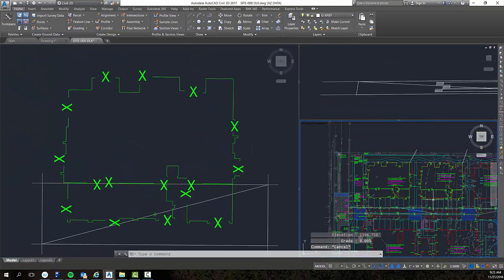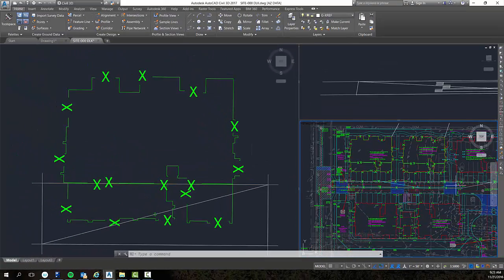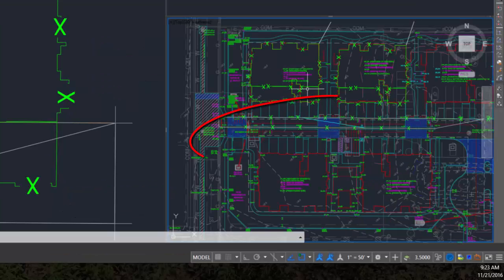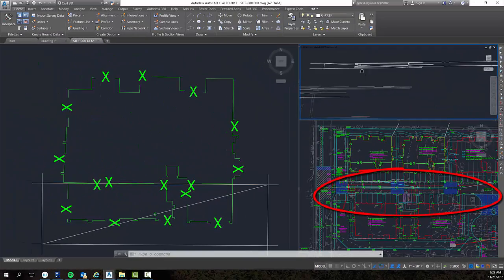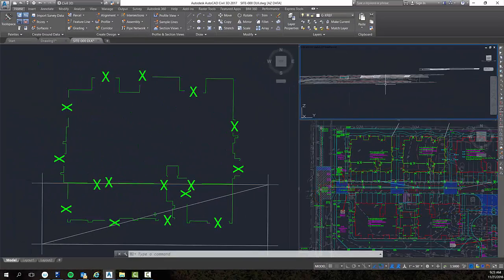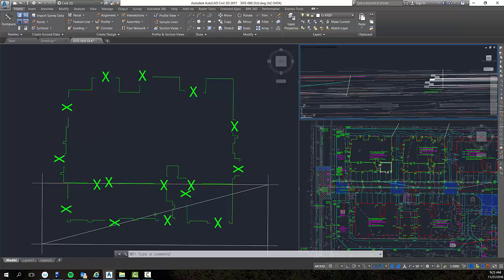So now at this point, we've got this surface here we've already started, so we can start adding this stuff to the surface, right? So let's go ahead and do that, and then we'll go to our next part here. You can see the surface here. You can see our new building envelopes at the elevations, and you can see them highlighting down there on the plan view. So let's go ahead and add that to the surface, and then we'll start working on some of the drive parking towards the building here.